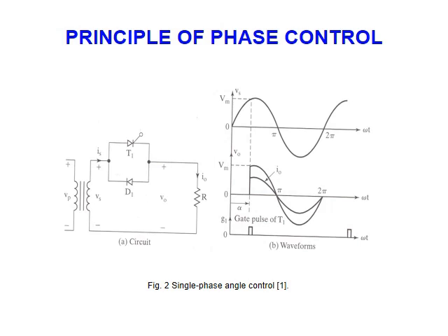Now the other method, phase angle control. First, let me start with half wave. So I have a diode anti-parallel with a thyristor. The second issue for this method is that we control alpha. Alpha is not anymore 0, and there is no N and M, no on and off cycles. It will continue, but we control alpha.